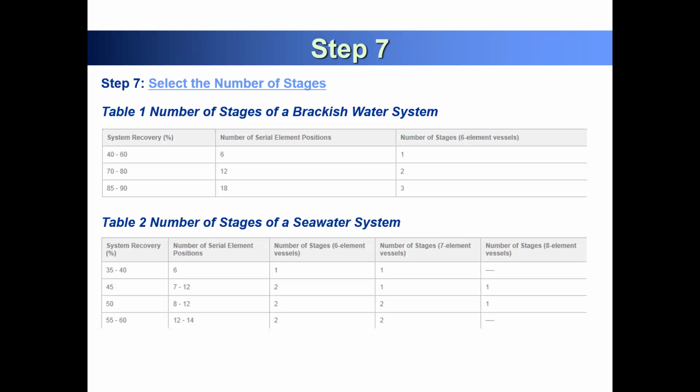So you can allocate stages as an effective way of achieving water recovery. But if you just want to go for 40 to 60% water recovery, you don't have to go for stages. Just the first stage, 10 pressure vessels, go one time, and you will achieve 50% water recovery. So for brackish water, depending on your water recovery, you can decide which condition would be the best way.